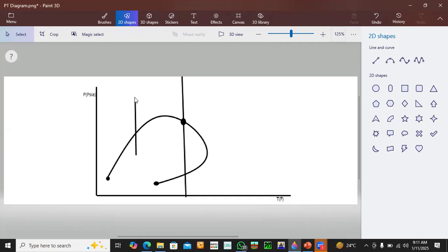So if the initial reservoir pressure is higher than the bubble point pressure, that reservoir is regarded as an undersaturated reservoir. All gas remains dissolved in the oil phase until it reaches this bubble point curve. So as pressure depletes, gas expands within the oil column, but it will not start liberating, or leaving the oil column, until it reaches the bubble point curve.